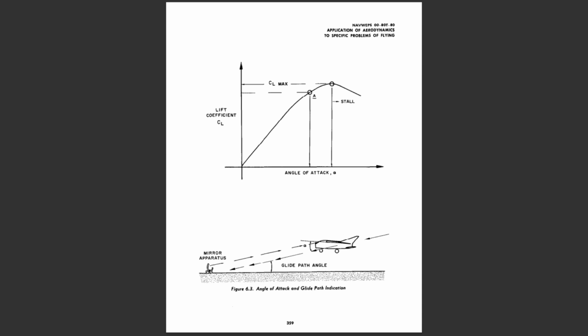When the airplane is flown in a steady flight path at the prescribed angle of attack, the resulting airspeed will be appropriate for the airplane gross weight. Any variation in gross weight will simply alter the airspeed necessary to provide sufficient lift. The use of an angle of attack indicator to maintain the recommended angle of attack will ensure that the airplane is operated at the proper approach speed, not too low or too high in airspeed.